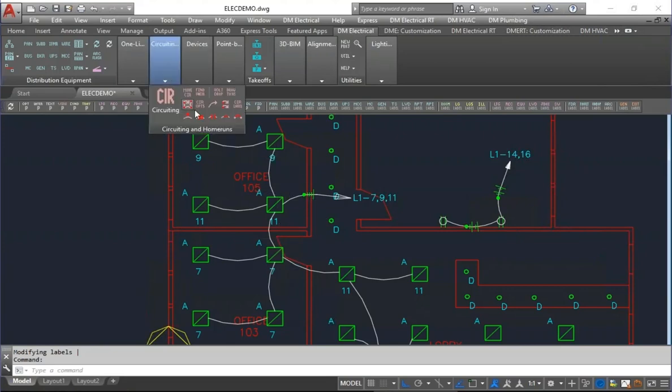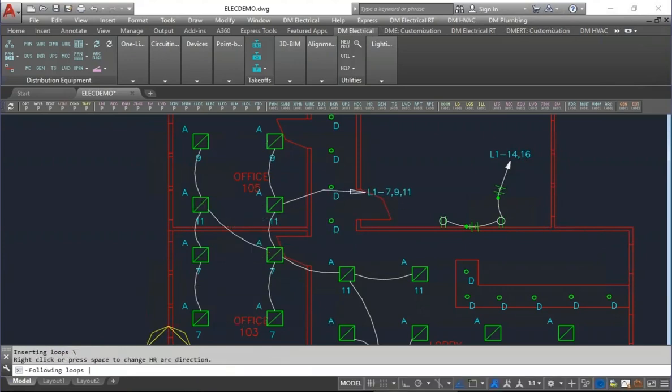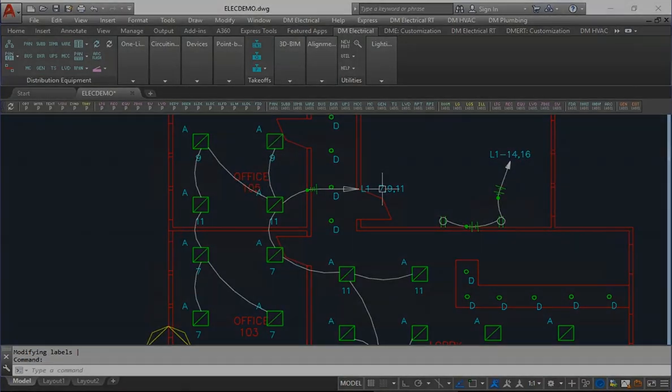You can actually do some more nonsensical things. You can say, okay, I actually want to prefer this diagonal angle. So I want to have my light fixtures connect diagonally first. And then you get something goofy like that. If I do a more 45-degree angle, I think we'll get, there we go. So you can give it a little bit of preference as to how to make the connections. That's what that command is for, and then the other one, the set center point, is for controlling the arcing.